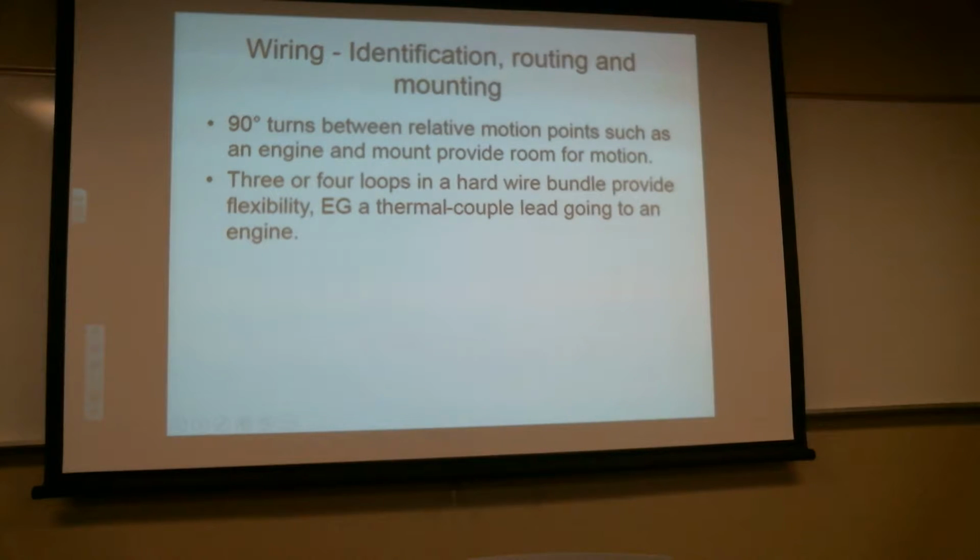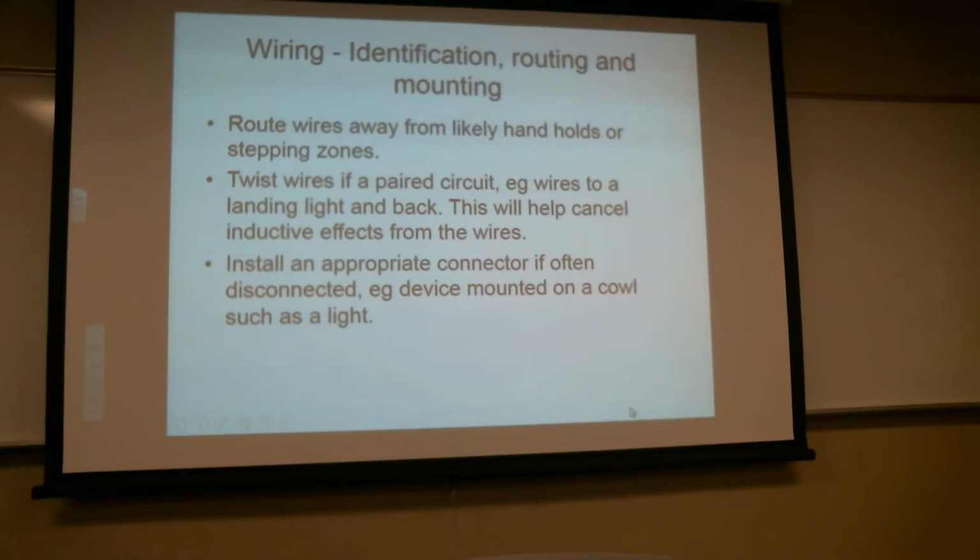Now that said, how long should it last? Well, thermocouple probes, especially exhaust gas ones, tend to get fried in the exhaust gases fairly readily, 500 to 1,000 hours, something like that. But on the other end of the coin, the CHT ones, they're much lower temperature. They tend to last for life of the engine at least.